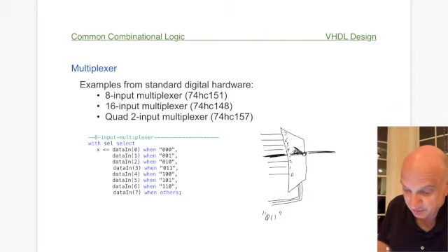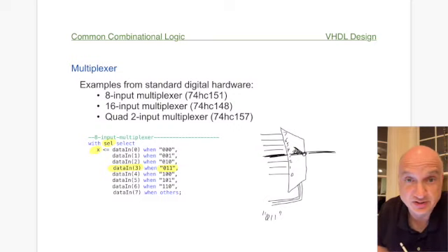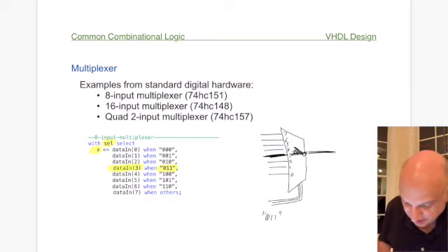So the same thing happens, or basically, to implement that function, we use a selected signal assignment statement. And basically, the selected signal assignment statement is made for multiplexers, right? There's your select line. That's what selects the route that you want. If we selected 3, then when it's 3, the third bit of the input data is routed to the output. And that's what this statement is doing. So it's basically assigning this to the output when the input on the select line is 0 and 1.